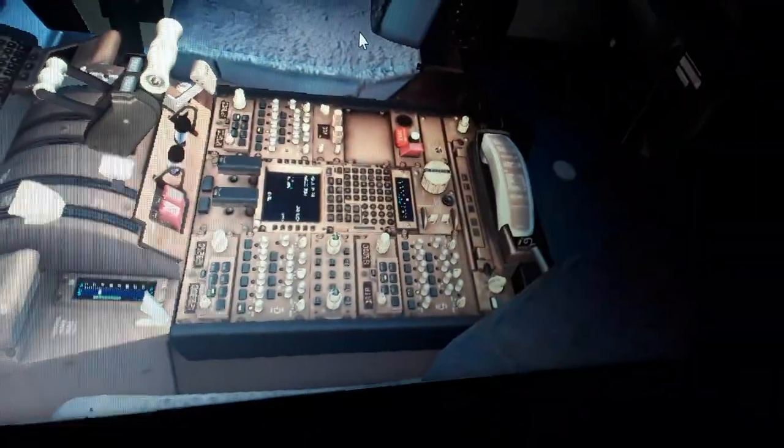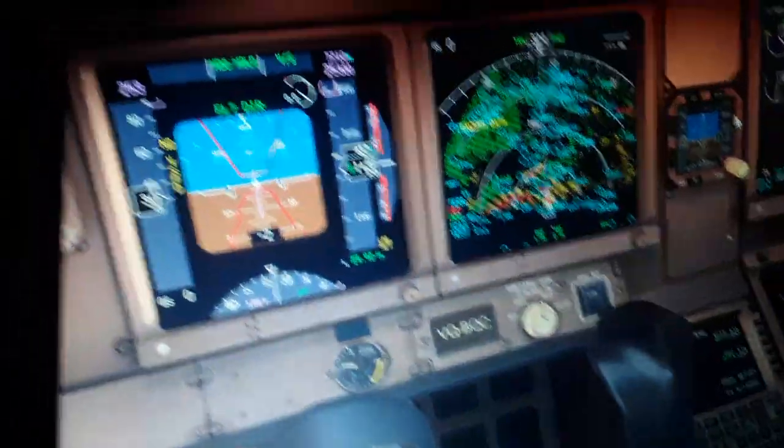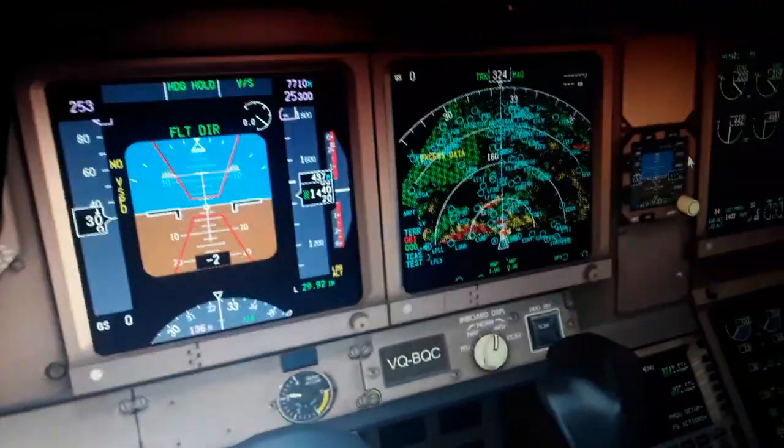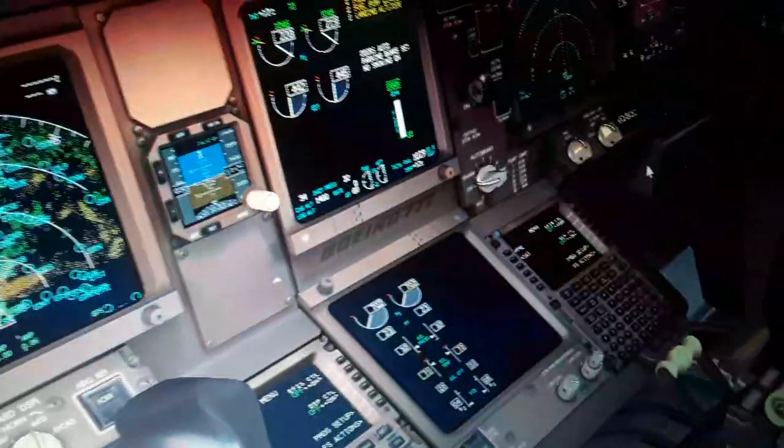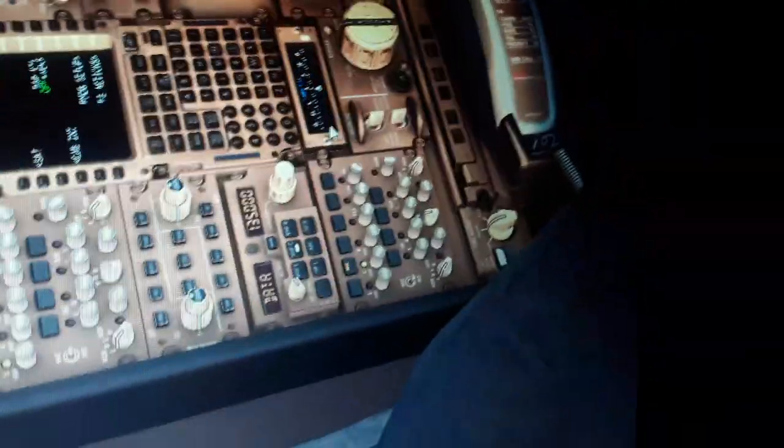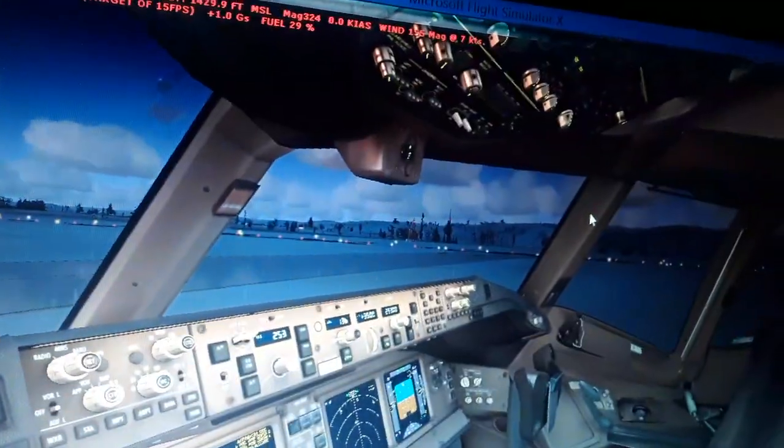Now we have also other systems: the radio communication panel, the transponder, ADS-B, and the TCAS system, which receives and transmits our position and other aircraft positions. It's a passive radar. On the display you'll see other aircraft and the warning. In the display we have collision avoidance, the other aircraft, TCAS pass. We have the weather and terrain radar here. So this is a few of the systems we have.